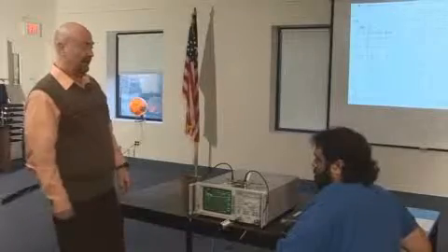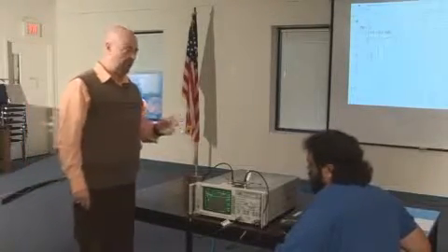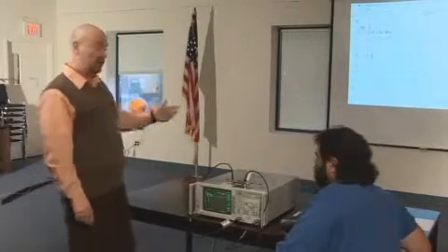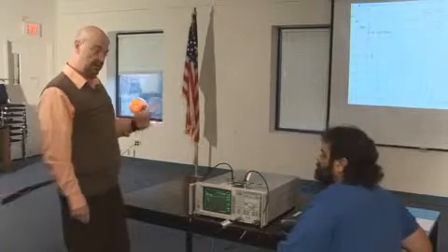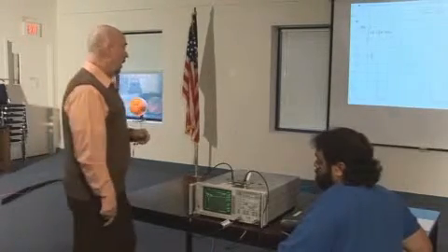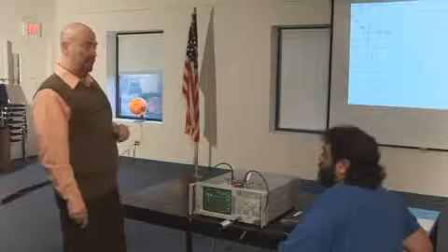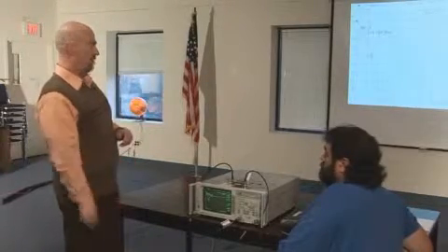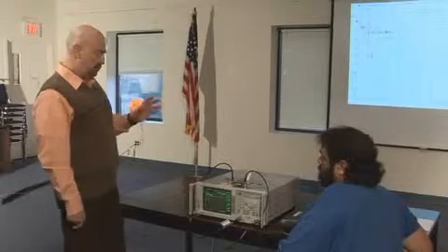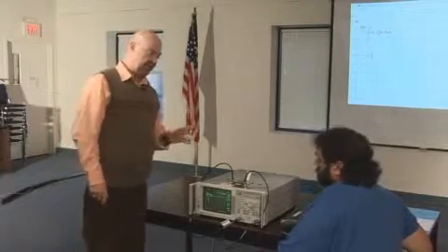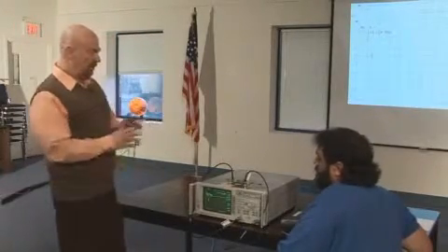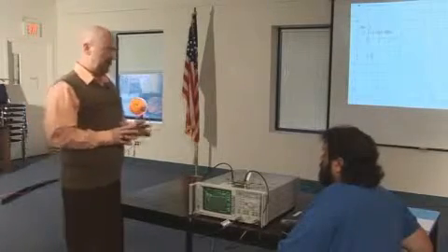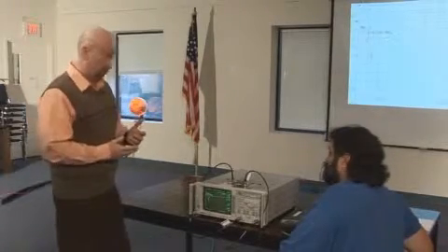So we basically are not attenuating the signal we want very much, if 43 was our intended signal to get rid of. And once again, as you go up in frequency, this mismatch becomes worse and worse. So generally, you want to keep your leads short on these devices. Great. Now, there are some other things we can do to mitigate this situation a little if you must use leaded parts.